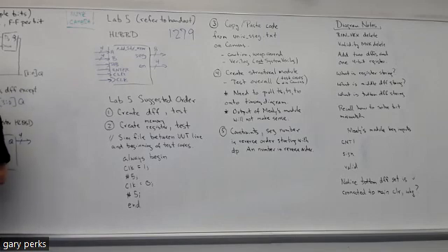Also, you want to check priority. Remember we said the priority is reset, then set, then loading. So how would you check to make sure that reset is the highest priority? Set them all to 1, yeah, just make all your inputs equal to 1, right? And make sure it resets. Did you have a question?